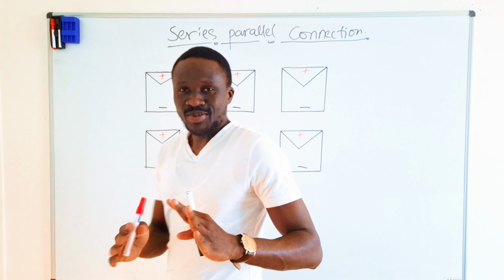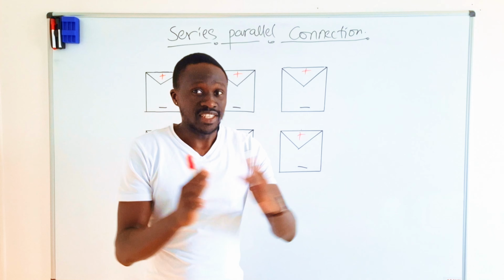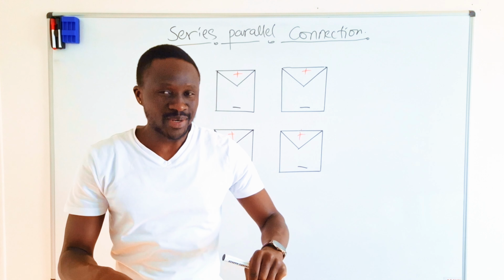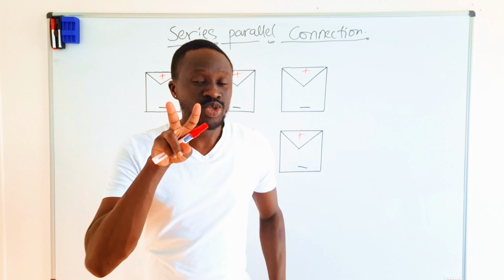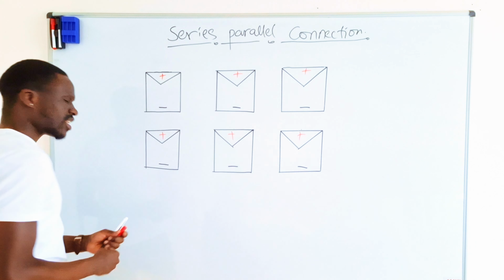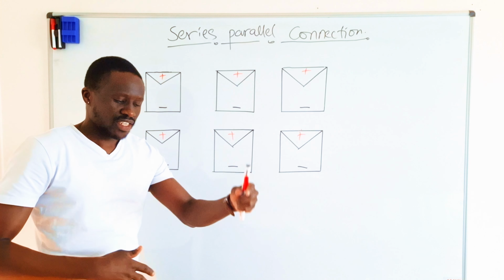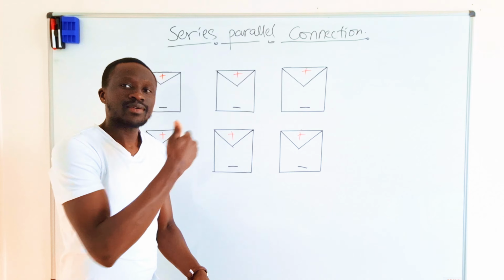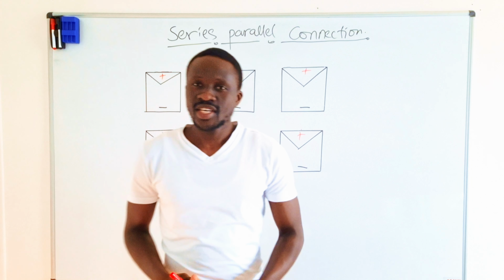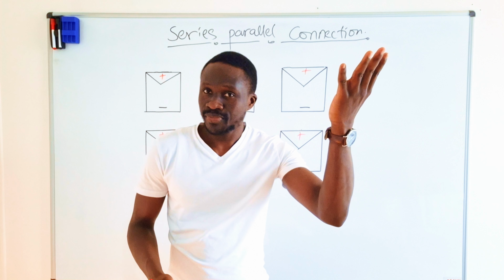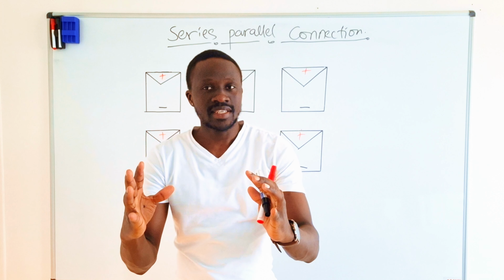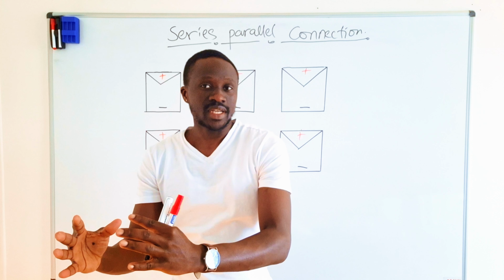Okay? As we are going to connect these things both in series first, then we connect them in parallel. And we connect this and we shall get the two terminals, the positive and the negative. Okay? Let us see. How do you connect in series parallel connection? Okay, what is the science behind? The science behind is we want to increase the voltages. That is the series connection, and we want to have much current to power our battery or to charge our battery.